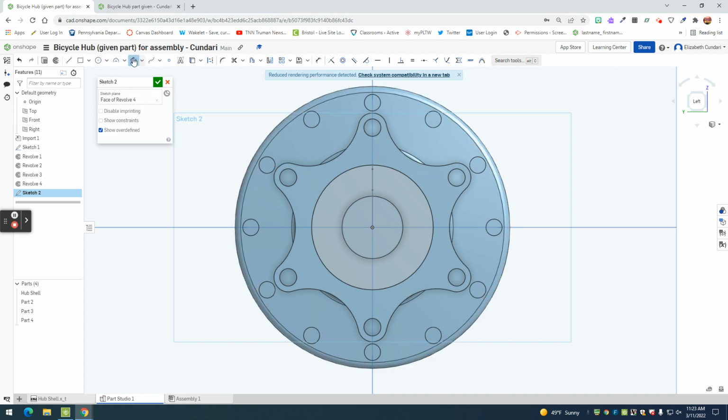we're going to use the hexagon, but we're going to go for 6-sided here. And make sure it's not tying into anything. Sometimes it'll turn yellow and tie into something, or it'll have another constraint. Don't let it have any constraints. Let it just be there. Keep it at 6. We can make this shape.